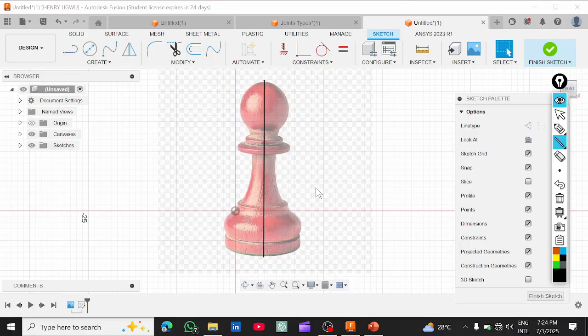If you have any geometry that is symmetric in this nature, you don't need to trace out everything because you want both sides to be equal and identical. The best way to generate such a design is to trace out one edge and create a revolve. You use the revolve tool to create a circular revolve, and that will generate the entire model for you without having to trace out everything. Our model is circular in nature, so we can trace out one part and then revolve it.